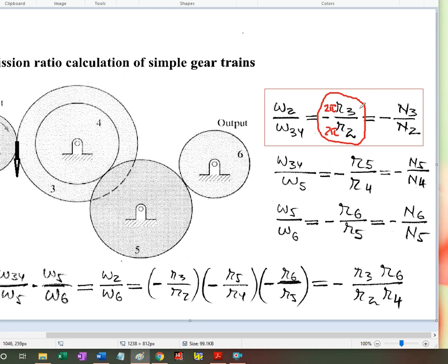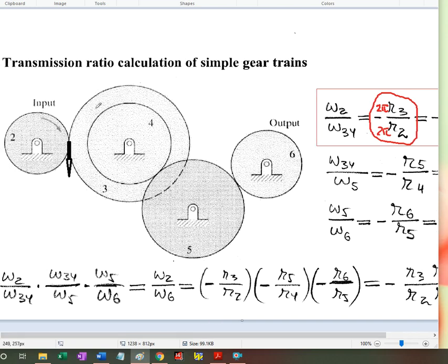Okay, now if I divide this circumference by what is called circular pitch, that is, for say number 3 gear, I have one tooth and another tooth, and the circular pitch, actually they should continue below because we said this is the pitch circle. Sorry for this, I'm going to erase.